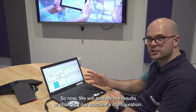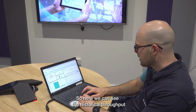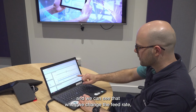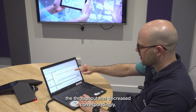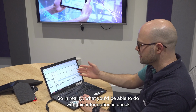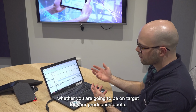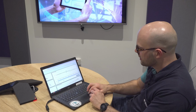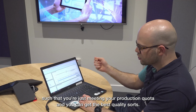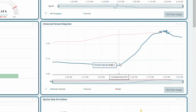So now we'll analyze the results of changing our machine's configuration. Here we can see the historical throughput, and we can see that when we change the feed rate, the throughput has decreased correspondingly. So in reality, what you'd be able to do with this information is check whether you're going to be on target for your production quota. So you could use this to fine-tune the feed rate such that you're just meeting your production quota and you can get the best quality sorts.